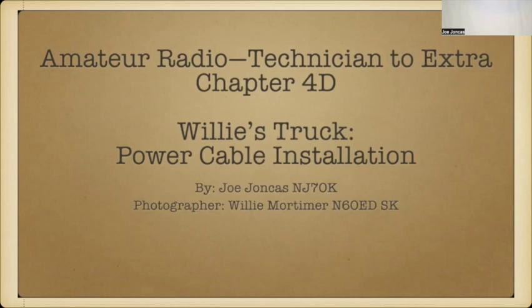So I talked about shrink tubing. Shrink tubing is some tubing, you slip it over the wire, you apply heat, and it shrinks to the wire. And the kind that I like is the kind that has glue inside of it. So that as it shrinks, the glue melts and seals the connection. And that way you make sure nothing can get into the connection.